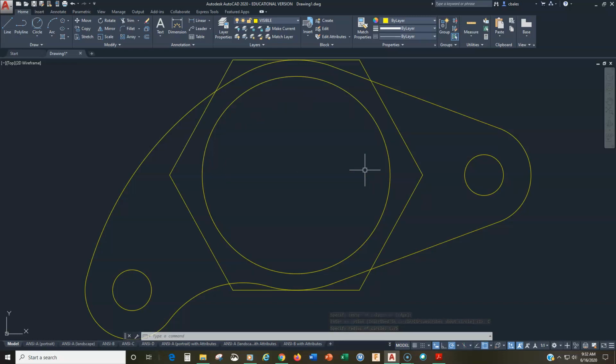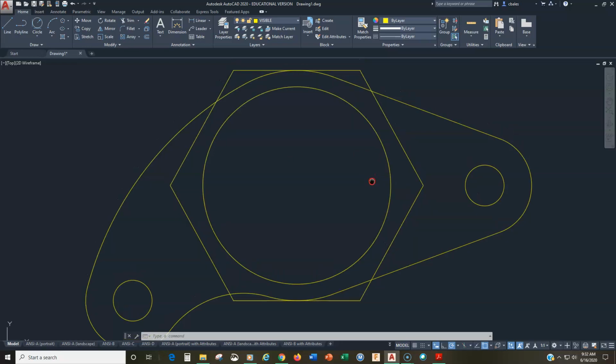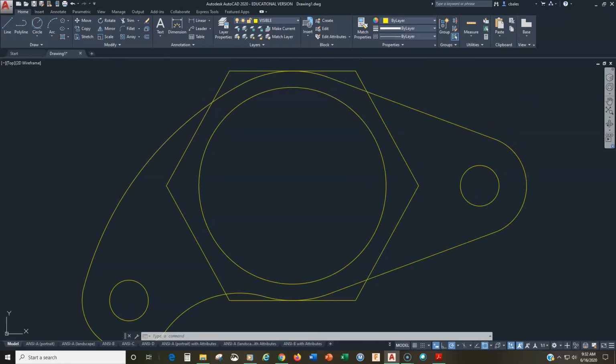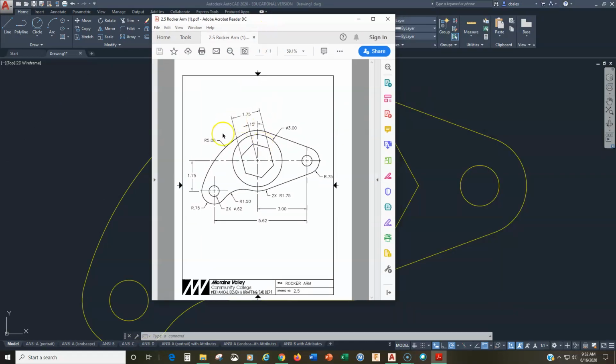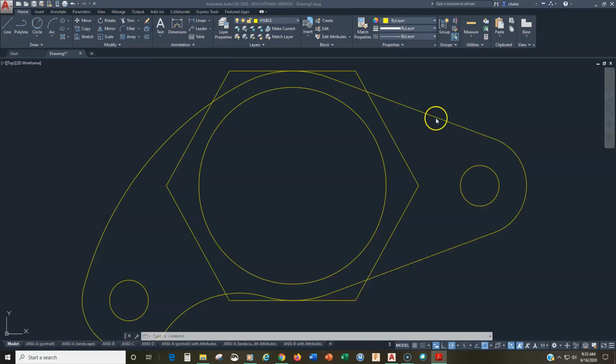You know, is Chuck's drawing wrong? What's going on? Did I type in everything right? Well, you didn't notice that the polygon was stretching half the width. Now I fault AutoCAD for this because it is very common for this dimension to be given as the full width across the flats. And so for them to switch it up here subtly leads to a lot of confusion, at least until it's explained to you. So there we go. All right, so let me get rid of that.